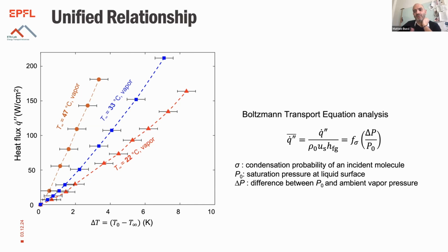I'm assuming that you have pinning on the mouth of the orifice. So to me, I'm not really surprised that in the end, increasing pressure on the vapor phase increases the heat transfer rate, which is, in my view, proportional to the contact line density, so practically speaking, to the number and the diameter of the orifices.